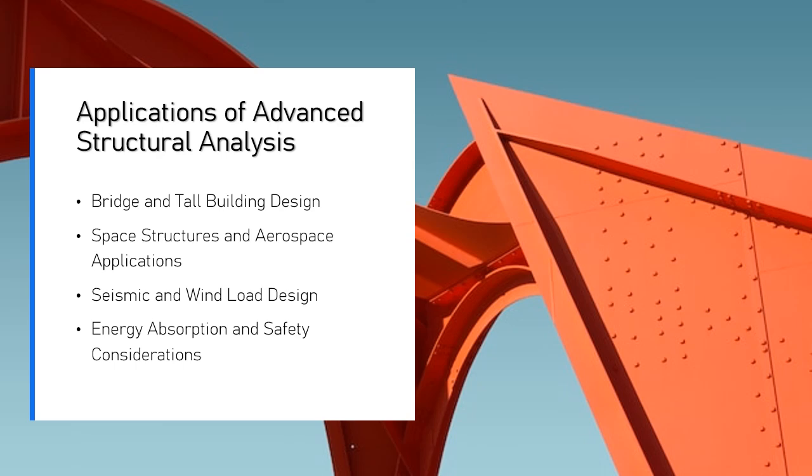Advanced analysis. Engineers often use multi-hazard analysis to evaluate how a structure behaves under combined seismic and wind loads. This involves stochastic simulations, Monte Carlo methods, and nonlinear dynamic analysis to understand the interaction between these forces. Outcome. The structural design incorporates safety features that account for both seismic and wind-induced displacements to minimize the likelihood of failure under extreme conditions.